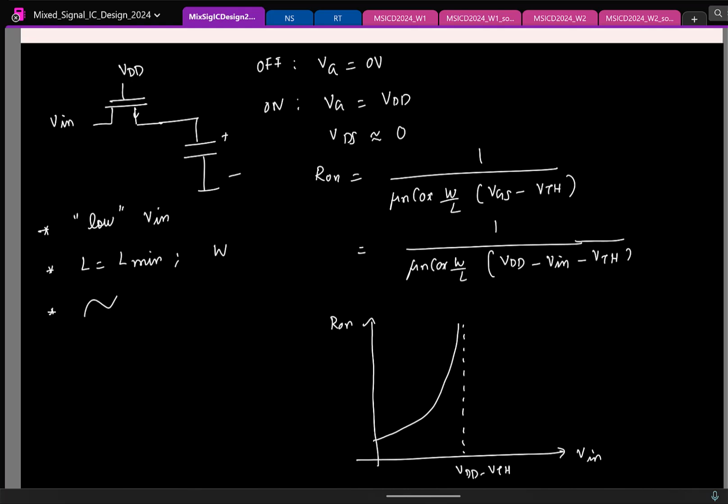You mentioned Vin is not in our control. Vin is a signal that you are sensing from some other circuit, right? So you cannot decide what my input should be. Fine. So let me write it. If you have a time varying signal, you'll have nonlinearity, and the only control knob you have is to keep this as small as possible.